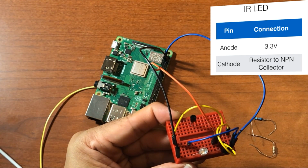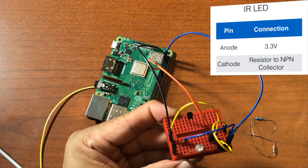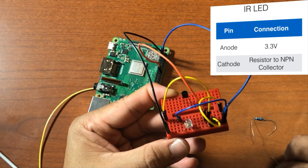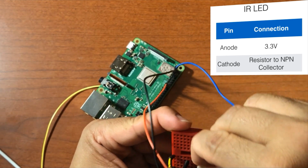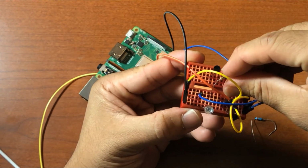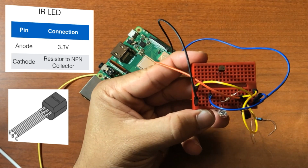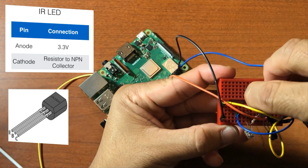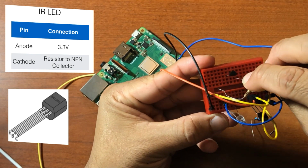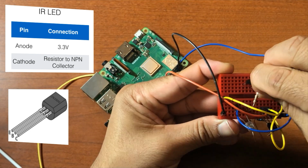From the cathode, we have to connect our 100 ohm resistor, and that is this one here. So the cathode goes to a 100 ohm resistor, and the other end goes to the collector of our NPN transistor, and that is the pin on the outside. So I'll make that connection here. There it is.